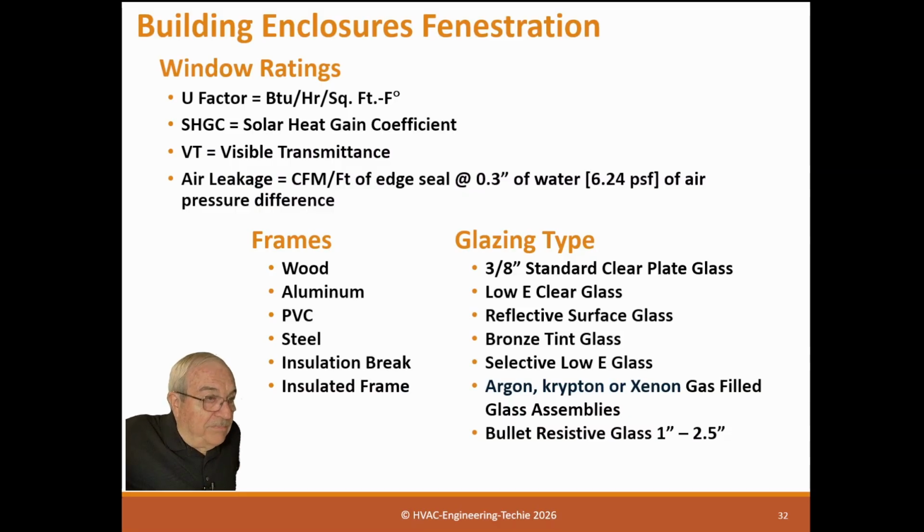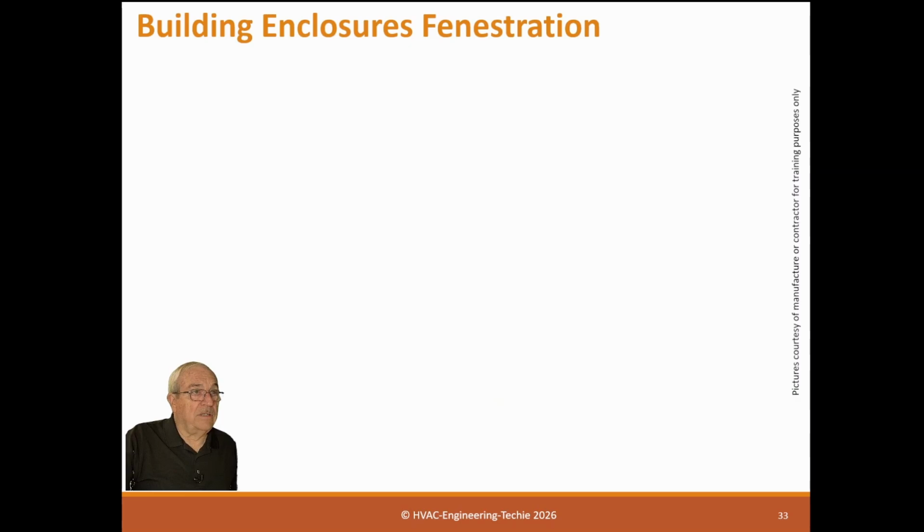It's not as heavy as tempered glass, but by the way, up here at 3/8 standard glass, most of this is tempered, which means it's gone through a heat treat process. That's why you see this glass shatters instead of cracks. It builds up interior tension until it just can't take it anymore. The whole sheet crumbles. They use tempered glass because it's stronger, of course, but second, it's not dangerous when it blows up. When a regular non-tempered glass cracks, the pieces of glass are sharp and cut very, very severely. So we use standard tempered glass everywhere.